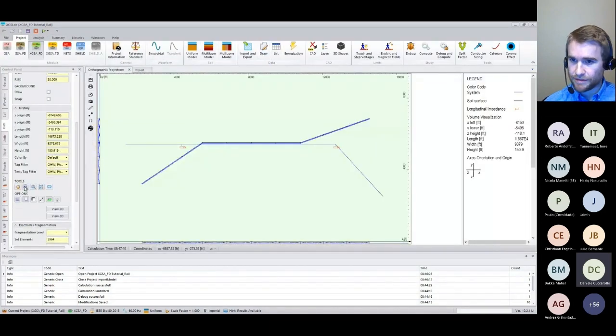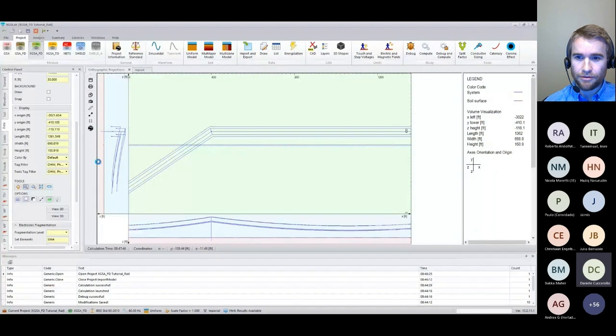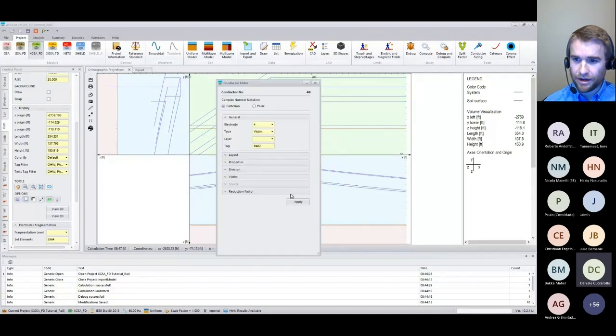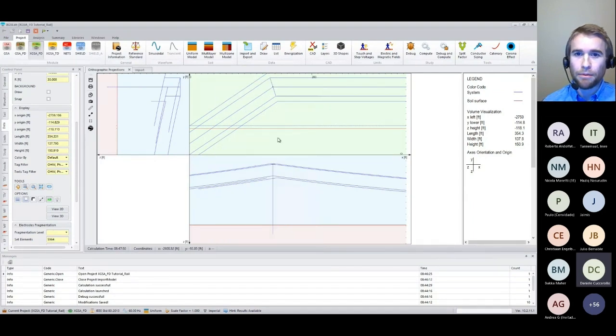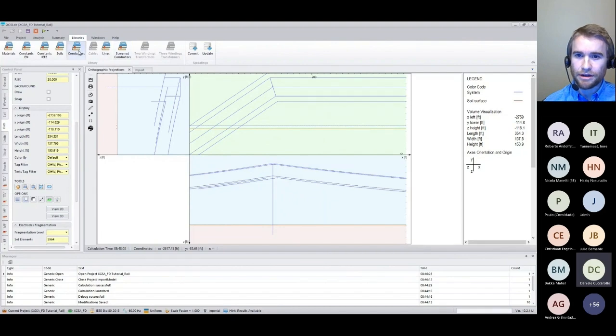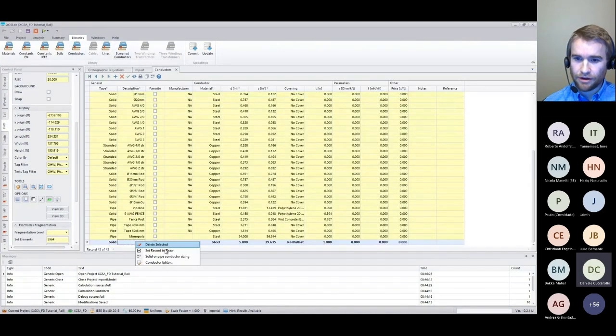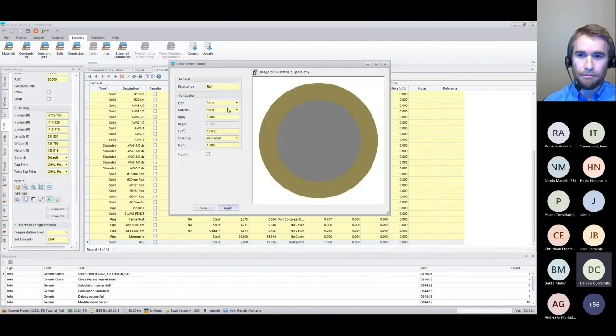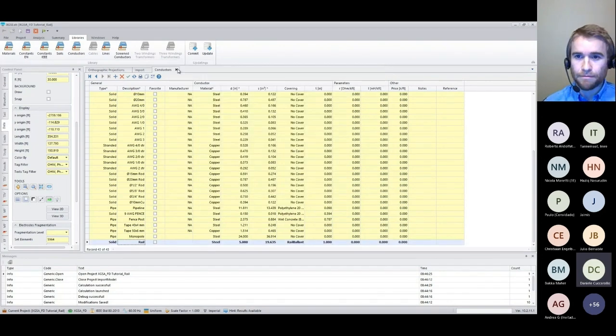So what we have is now a railroad model that we're going to look at for steady state induced voltages. And the railroad differs from the pipeline in that instead of just one conductor, we now have two conductors along this path. So if I click on this, we can see on my conductor editor, I drop down to my properties. This is my rail. And that property is assigned through my conductor libraries. And this rail characteristic, going to conductor editor, has a steel metal, and it's covered with a rail ballast. And the rail ballast has to be approximated in the software.